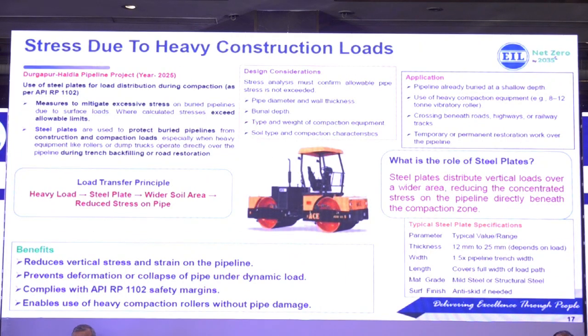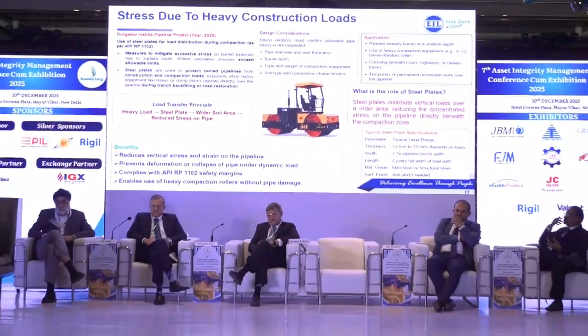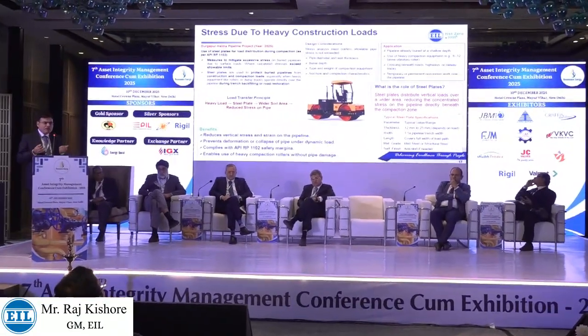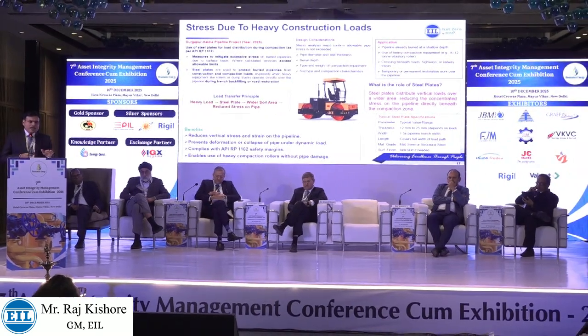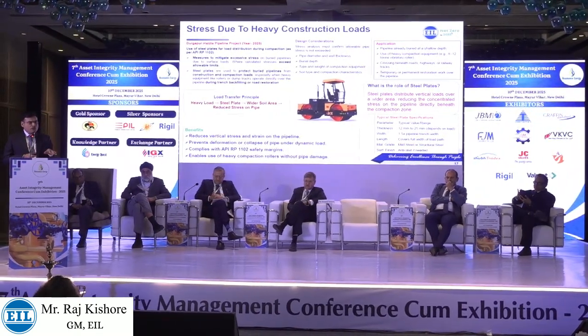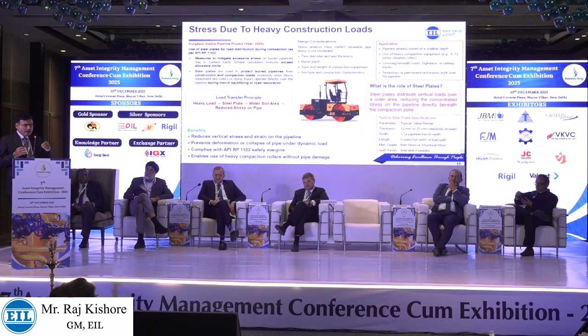Regarding stress due to heavy construction, recently we were laying a pipeline in the Haldia region, West Bengal. We laid the pipeline and the PWD authority came and told us they were immediately going to construct a road, while the pipeline was still unbackfilled. They told us to just backfill it, as they were going to put their rollers and big vibratory roller machines and construct the road. We said that directly putting a vibrating roller on it would damage the pipeline. So we designed a solution.